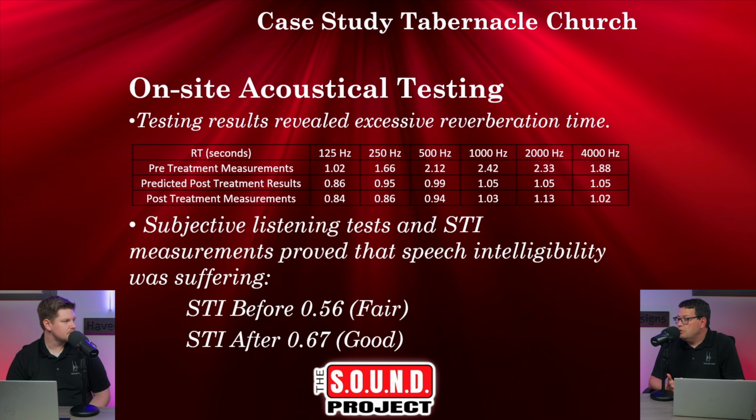Okay, so now we're going to show a little bit of the acoustical data that we took, because this project being in Troy, Ohio, it's only a couple-hour drive from here, and so I had the ability to do testing beforehand and after the acoustical treatment was done. This chart shows the reverb time from 125 hertz up to 4,000 hertz. The pre-treatment measurements are around 1 second at 125, 2.12 at 500 hertz, 2.42 at 1,000. So up over 2 seconds in a big chunk of the mid and high frequency range.